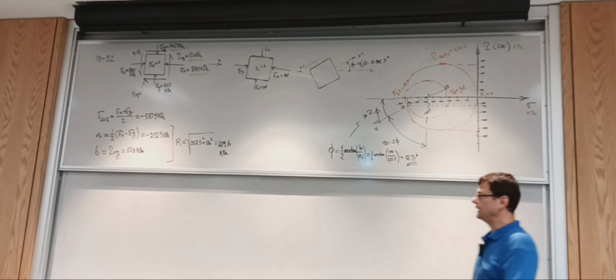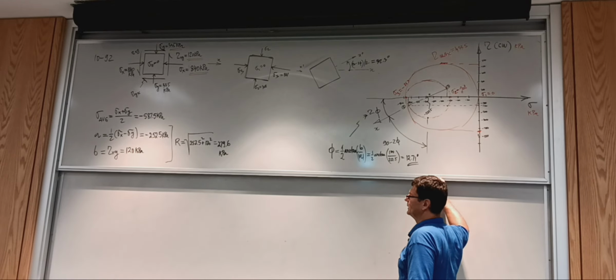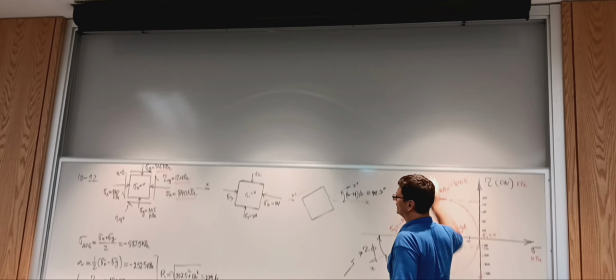We know that bending stresses are always the more severe stresses, unless you work locally and you have stepped shafts. But this one is a constant section, so we use bending stress as the predominant load, select the channel, and then evaluate the shear stress.